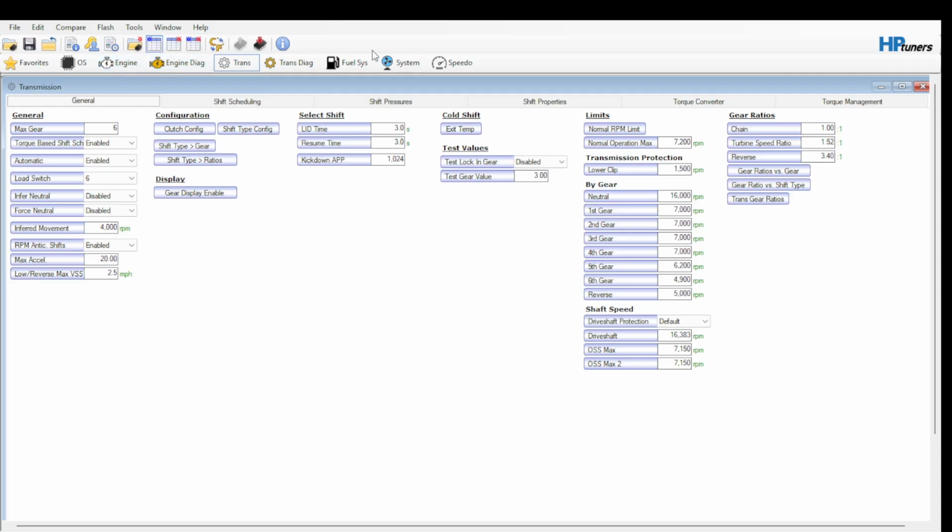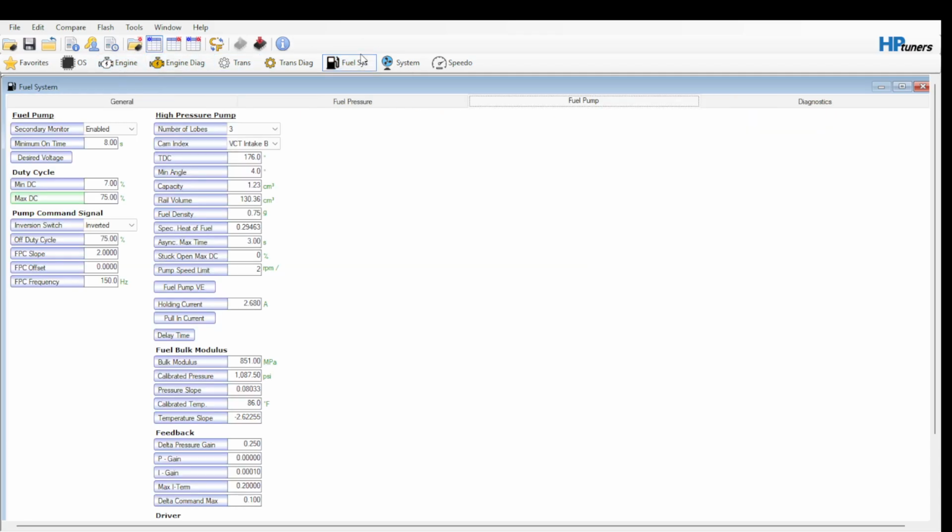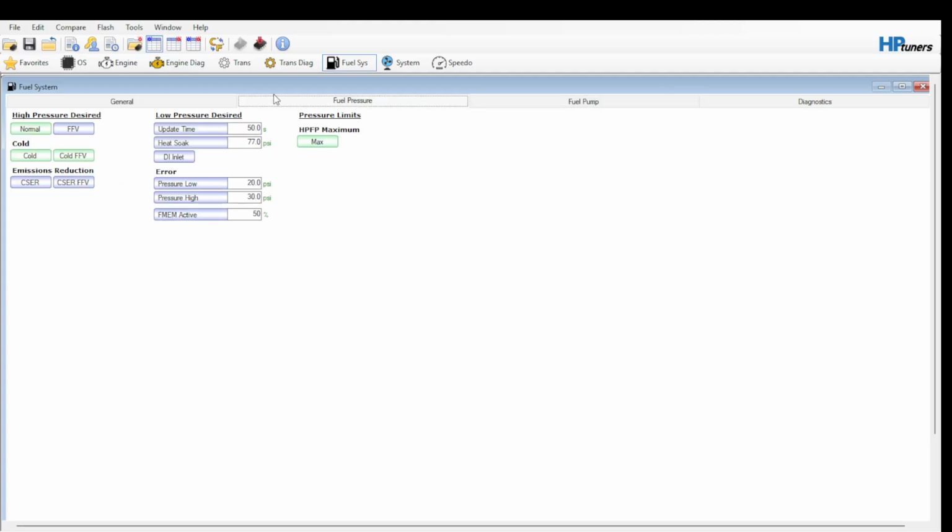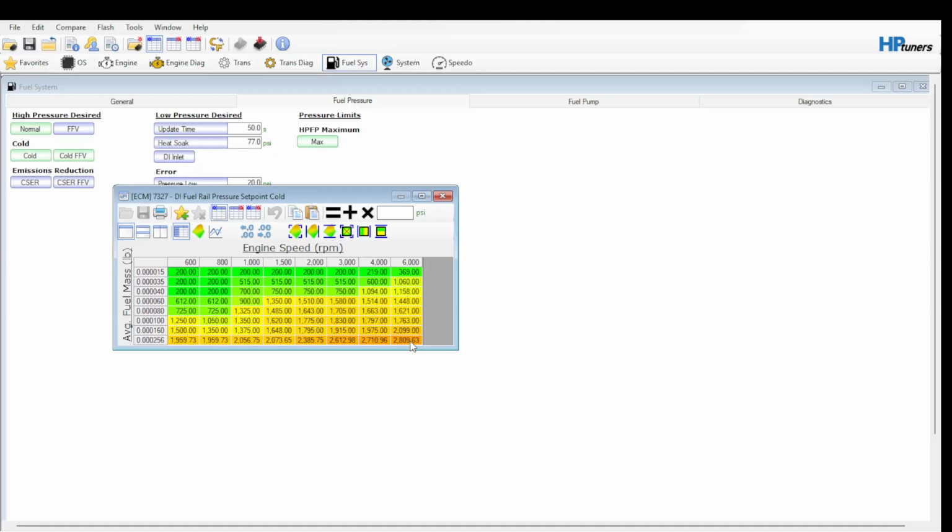But yeah, that's going to cover most of the things that I see coming out of the tuning, just generally. The other thing that I see people do is they like to really push these pressures quite high, but there's a more important thing that I'm going to get to. So hang around. I have pushed these PSIs considerably higher than stock, but I've also pushed them higher than this. I've pushed them up to, I think, 3,500 PSI, and they don't get there. And you shouldn't try to get them there, but don't worry, these injectors are extremely well built.